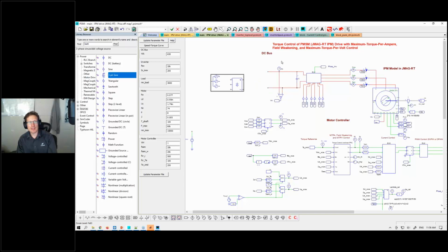And obviously, if this DC bus voltage is now varying because of this, we will see the controllers working to maintain proper Id/Iq set points, and we'll see the impact of that varying DC bus when we try and hit on the efficiency maps. So that's a perfect example of why you need a stable control system, which is what the design suite will give you, so that you can look at those sorts of simulations and look at your efficiency points at those points while ensuring that everything is working properly.